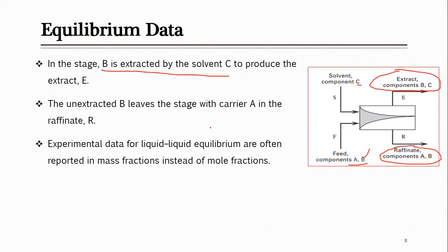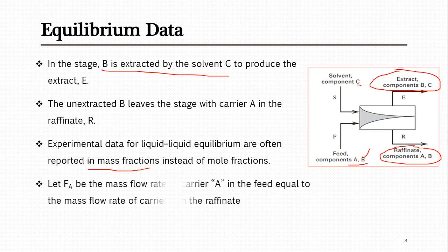So experimental data for this liquid-liquid extraction equilibrium are often reported in mass fraction instead of mole fraction. So now we have to look at some equations. We will be considering mass fractions and mass flow rates instead of molar flow rate or molar fraction, because these are liquids, and you know that in most cases when we are dealing with liquids, we talk about mass. But if you are going for gases, definitely they are represented in the form of moles and mole fractions.